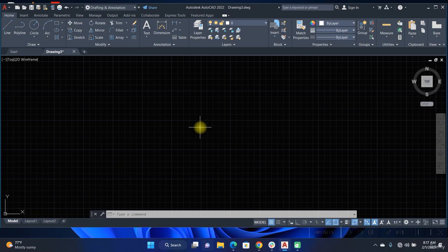Because if you don't put it off, then if you need to enter a coordinate for a particular line or a particular object, it will go somewhere else. So you have to put that in mind. Then I have the Ortho, which shortcut is F8, is used to have our drawing orthogonally. It restricts it orthogonally, that is in 90 degrees.